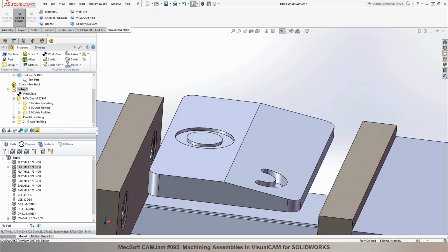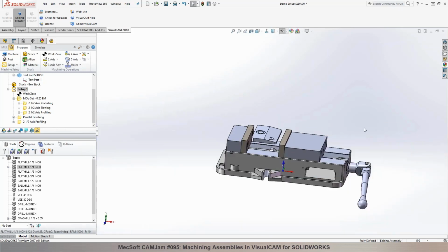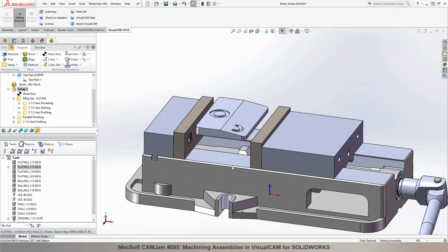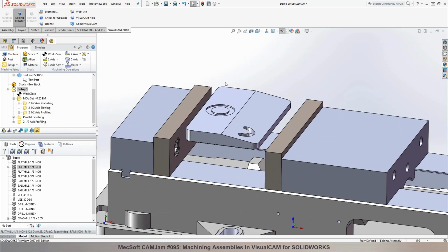So do you also have backlash correction? Because we're using this Grizzly benchtop mill, and that thing has Acme screws instead of ball screws, and I understand that backlash correction is kind of an important factor. I believe that's something you would set up in the FlashCut control program, how to account for backlash. I know in Mach 3 there's a setting, so I'm sure there's a setting in FlashCut, so you can certainly talk to FlashCut and they can.